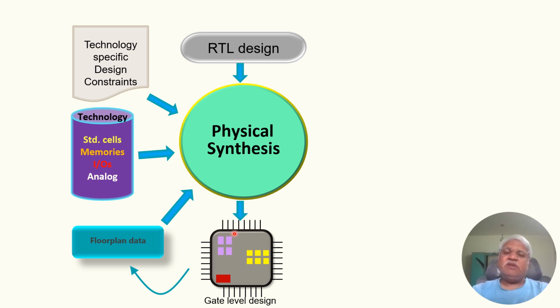Now it will take these macro data and the RTL and it will go for one more route. So during this time, you will get a better digital implementation, which is shown in the pink color. Now this will be a better representative of the RTL design with respect to the design constraints and the technology data provided.